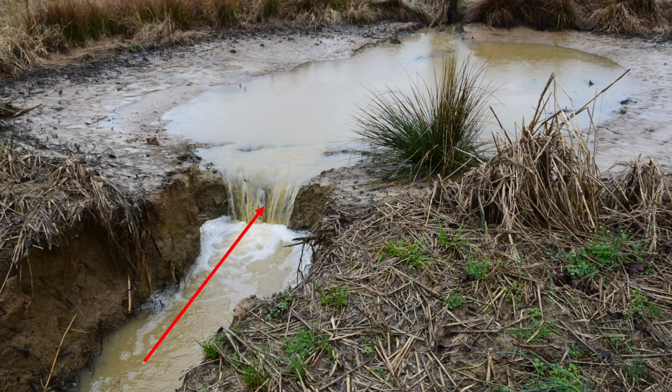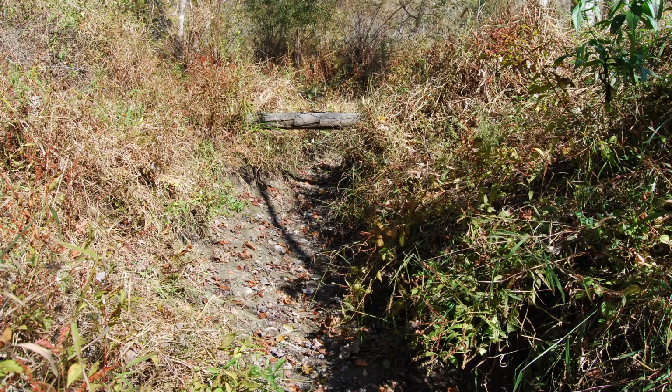This wetland was built without a spillway. Water flowing over the dam created a head cut that cut through the dam and drained the entire wetland. This photo shows where a beaver built a channel down the center of a spillway that had been constructed for the wetland. The deep and narrow channel is lowering the elevation of water in the wetland by 18 inches.